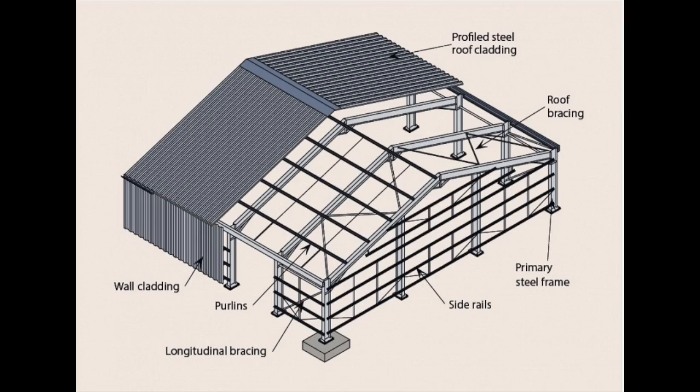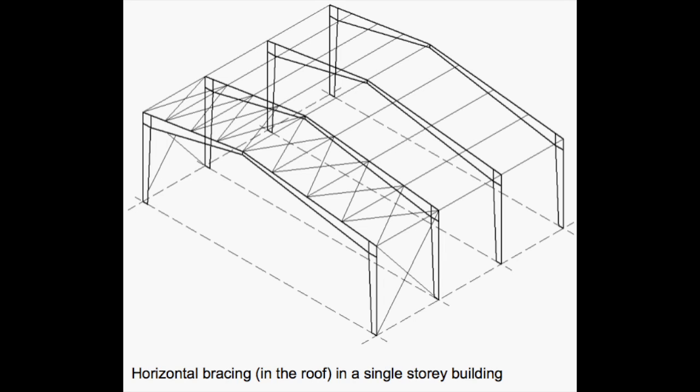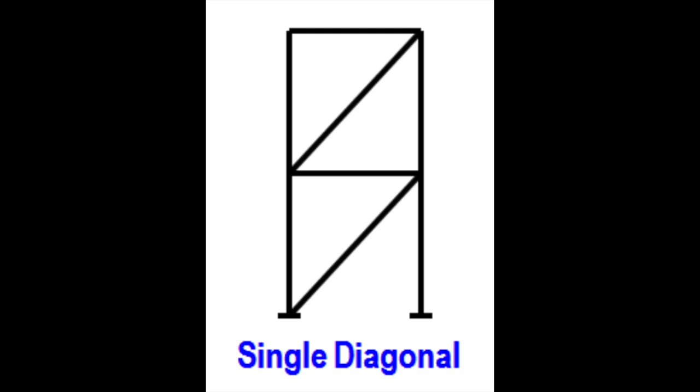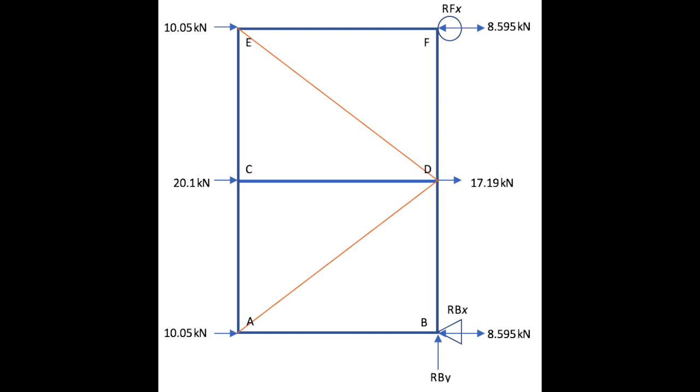As I completed the bracing design, I learnt that bracing is required to resist lateral loads arising due to wind loads acting on the structure. Roof bracing is used to transfer the lateral loads to the wall bracing and then to the foundation. Single member bracing was designed to support the loads in compression and tension. The diagonal bracing subject to compressive forces was eliminated for the purpose of this report.